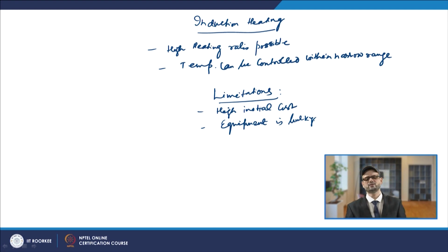And there are other challenges. For non-uniform wall thickness and geometries, there are certainly some limitations. Many times you need extra coils, so you have extra setups required. Certainly those points make it somewhat uncomfortable for the welders or the person handling it. So, that is about the induction heating methods.